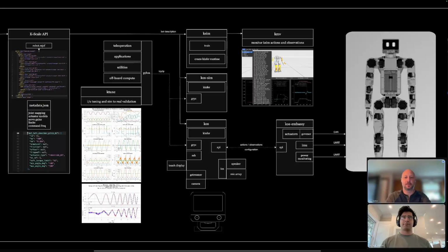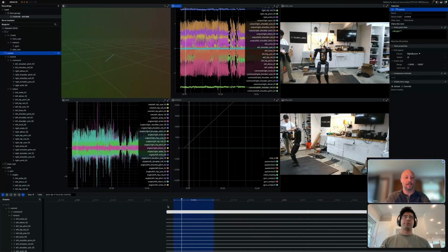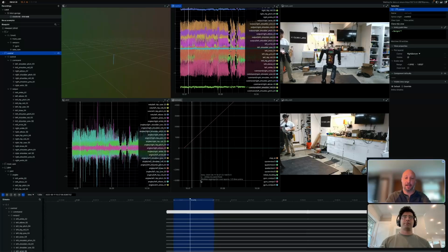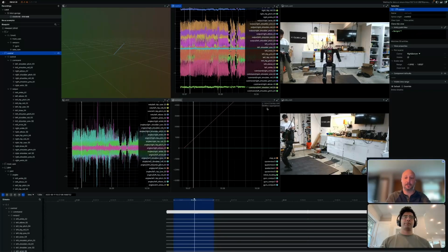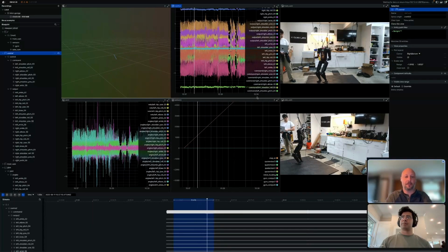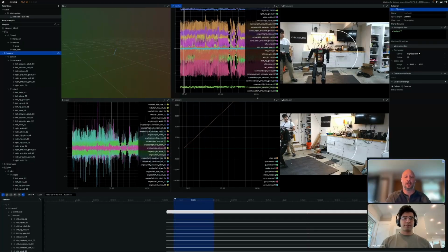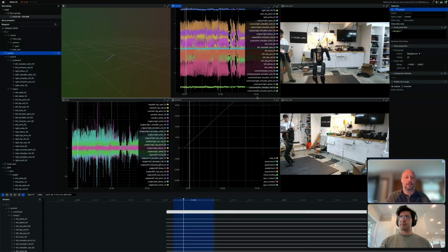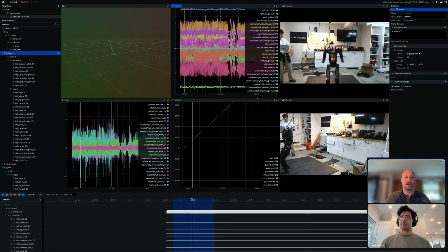Once we've verified our policies run smoothly in simulation, we can now run it on the real robot. Deployment is simple. The robot boots Linux and the KOS overlay, which runs the K-Infer policy and all the I/O on a deterministic and low latency path. So observation to action timing is predictable. KOS also offers a best effort gRPC channel for monitoring and configuration, all while keeping the entire stack running on off-the-shelf hardware. The deterministic policy to hardware loop you verified in simulation now runs unchanged on the real robot.